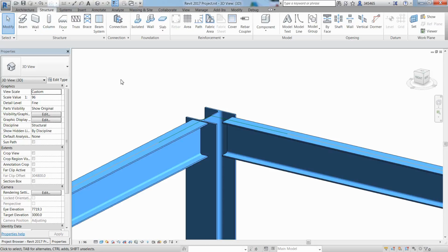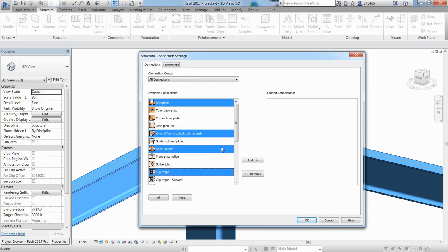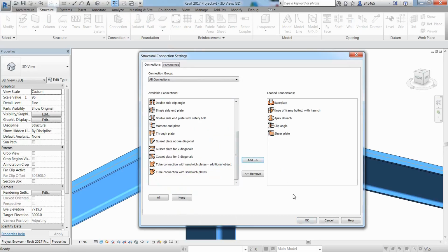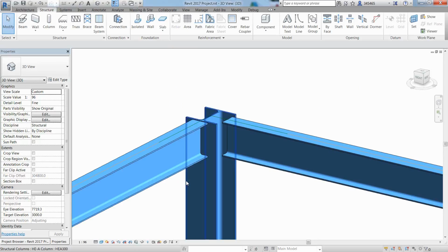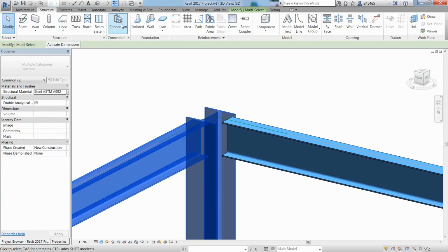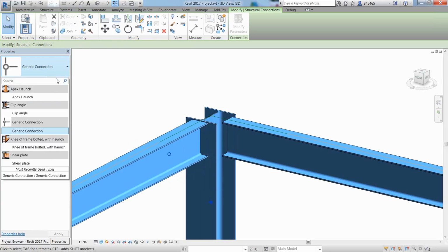One of the new announcements in Revit 2017 is the ability to place steel connections directly on the structural sections in your Revit model. You can download and install the Autodesk steel connections from your Autodesk account. The steel connections for Revit provide access to a variety of parametric steel connections, enabling connections to be modeled with a higher level of detail.